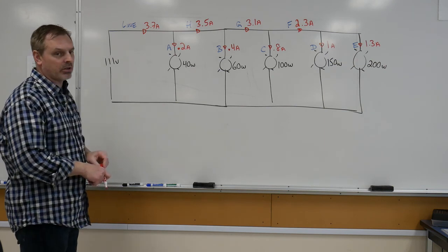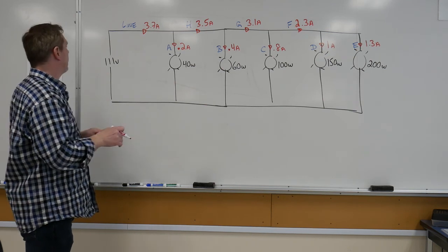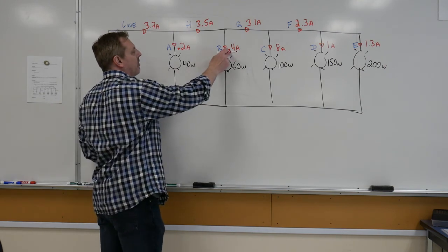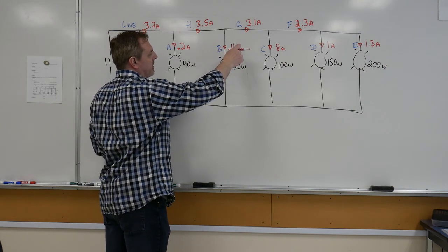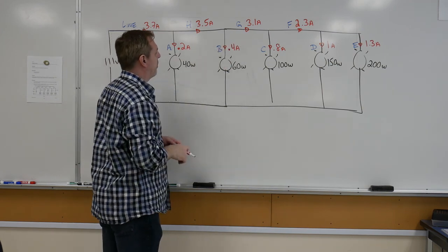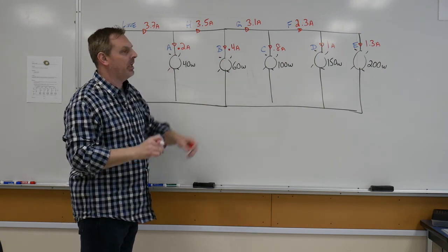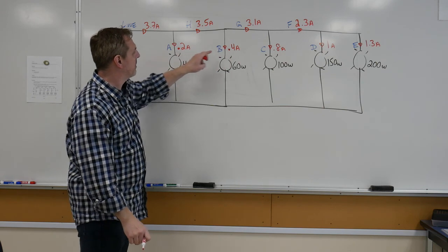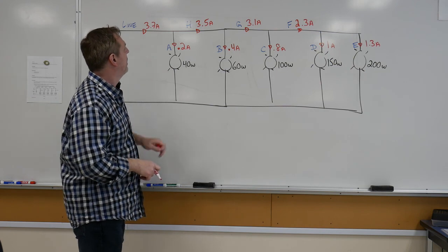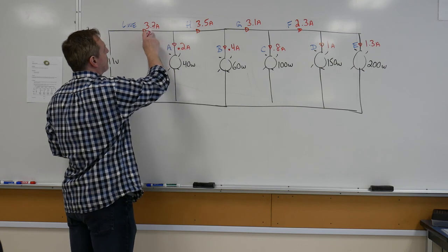Now, I know initially when I took some readings it was fluctuating between 3.7 and 3.8. I might have initially written down 3.8, or some of these values might have been roughly either 0.35, 0.36, or 0.34, so it might have rounded up to 0.4 there. The problem with the digital meter I was using for the ampacity is that when we're getting into these finite little currents, there's some rounding that goes on inside. But overall, the 3.5 plus the 0.2 gives us 3.7.